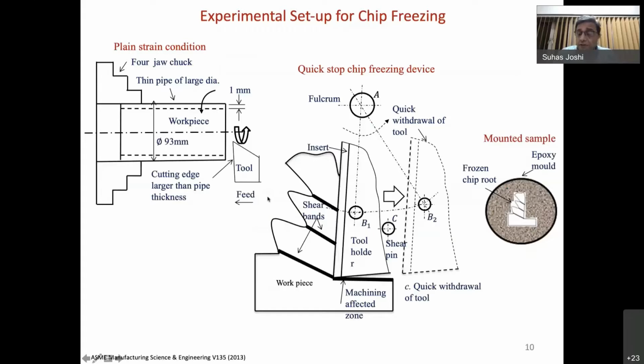One of the very traditional tools used for understanding the fundamentals of what is happening is this: the wedge is moving. While the wedge is moving, we simply take the wedge out of the machining process and let the partially formed chip remain on the surface. I'm showing it representatively here, but it is on a turning operation. Say, for example, you are turning. What we do is take a pin and rest our tool on this particular pin, and we perform the turning operation.